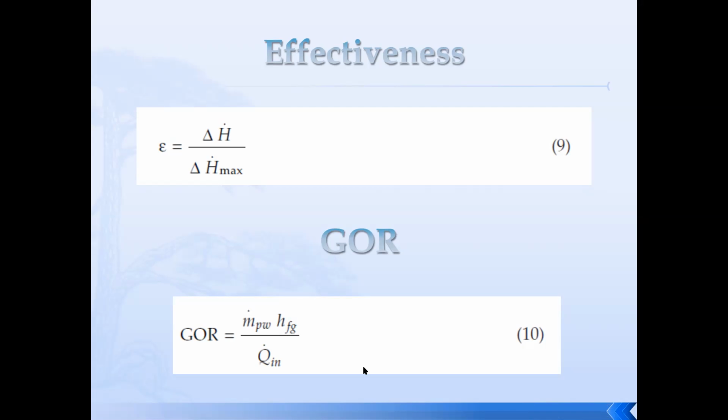I added a video last night to the Blackboard that is showing our unit that we have in our desalination lab. And the unit is operating by rejecting heat from a vapor compression refrigerator or air conditioner or a heat pump unit, and the condenser has been replaced. Instead of an air to refrigerant condenser, we replaced it by a water to refrigerant condenser. So as the refrigerant is being condensed after leaving the compressor, it gives off the heat to water, and water enters into the humidifier. So that is the source of energy, which is coming to the unit.